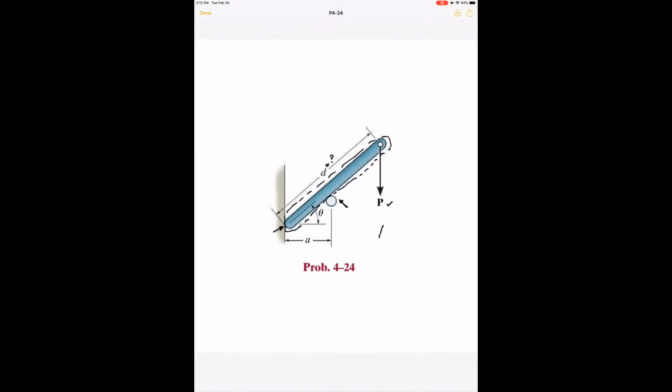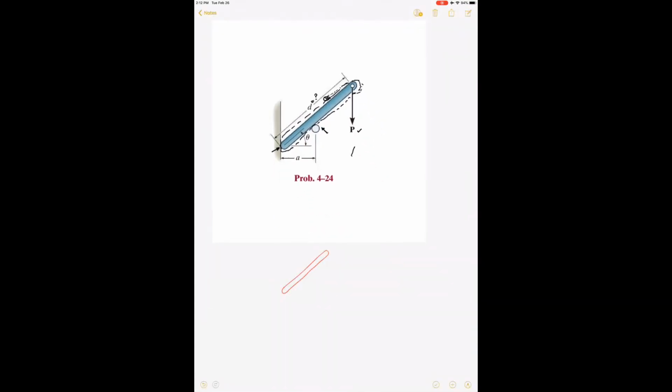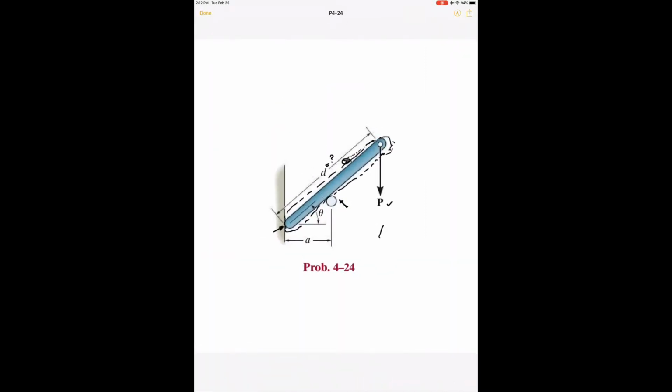There you go. Now I start walking on this surface to find the surface force, and then I add body force, and then I'm pretty much done with the free body diagram. So I start walking from here. The first thing I cut is this force P, so I have to include it in my free body diagram. So let's use blue to include the external effects. So there is a force P here, and then I continue walking.